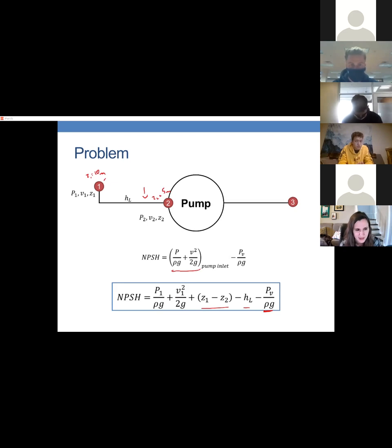Rankin, was that you? Kind of quiet. But I think you said more likely, and that's right. Because if some of the energy went into raising the fluid up, then we have less available NPSH going into the pump.